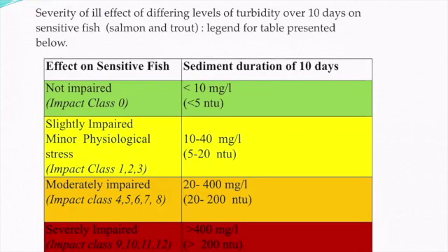If we look at a small tributary with a discharge of 5 liters per second, bringing dirty water of about 100 NTU down to a large stream with 30 cubic meters per second, the impact on that little tributary stream would be very different, less than 100 NTU increase, than the impact of the site on the intake on the main stream channel, which would be only about 0.16 NTU increase. Overall watershed impacts are not necessarily the same as local impacts, but it's something people often don't recognize when they're doing these types of assessments.